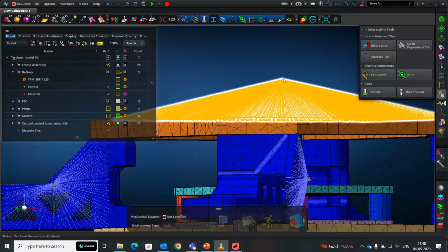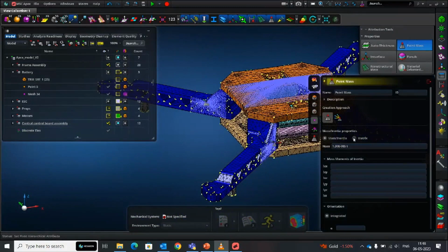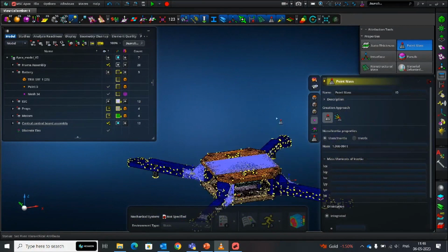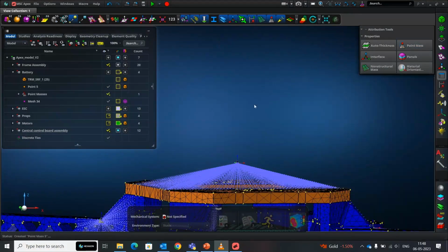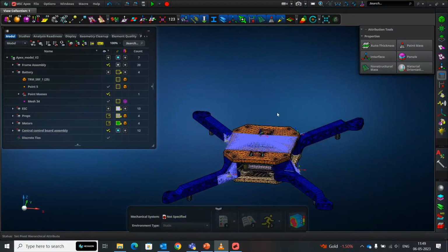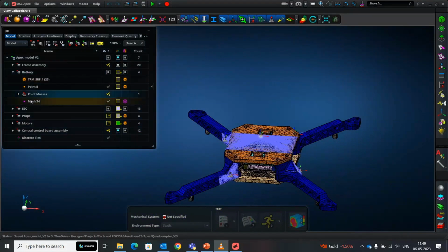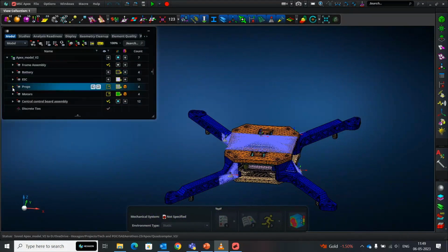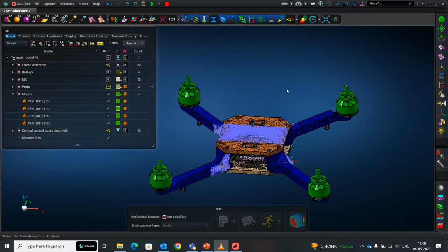And here I'm going to go ahead and assign the mass in this region again. So I'm going to have a point mass. This mass, I have evaluated it. This analysis is in millimeter ton second Newton Kelvin, so I'm using the same unit system. You also have the ability of changing the unit system to SI. You can change it to any imperial units, whatever you like, all within Apex itself.